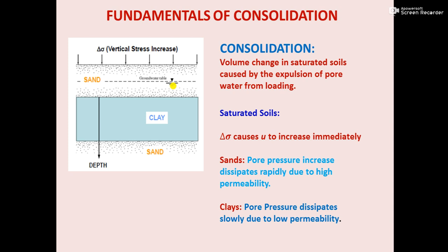So when it will not allow the water to leave this clay portion very fast, then what will happen? Then the water will have to take up this pressure, because in case of sand, as soon as the increase in stress comes to the water, it finds some way or path inside the sandy soil to move out.